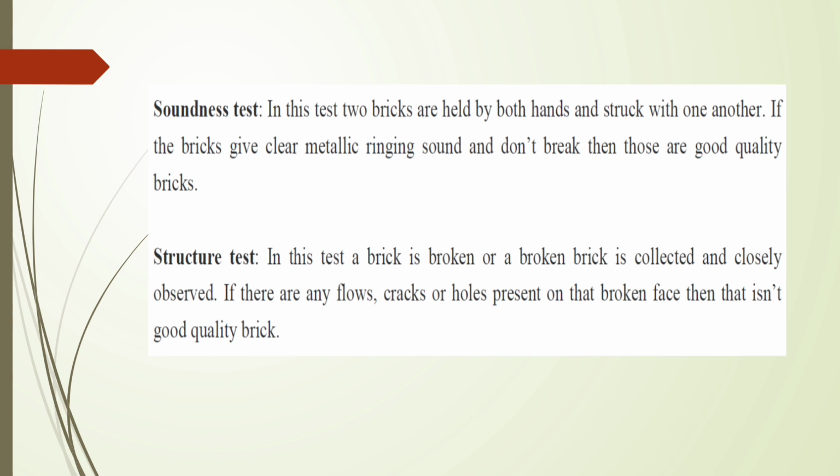Structure test. The fractured surface of the brick is examined. It should be homogeneous, compact and free from any defects. In this test, a brick is broken or a broken brick is collected and closely observed. If there are any flaws, cracks or holes present on that broken face, that is not good quality brick.